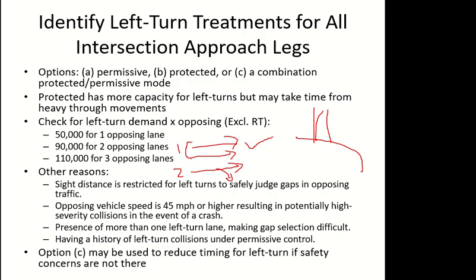So I'll pick for design the V by S ratio which is the most critical one. The critical one is the highest one. The lane which has the highest V by S ratio will be picked as the critical one for each phase. So all three lanes will have one phase, which is for the straight movement.